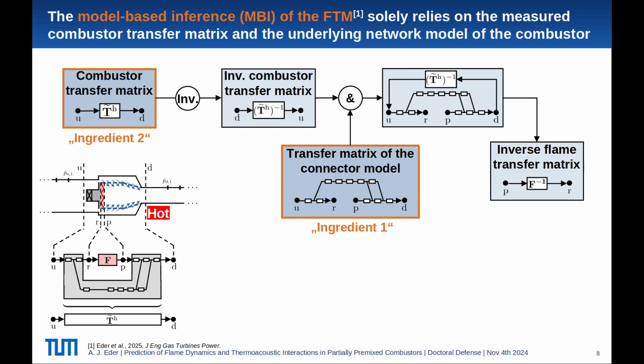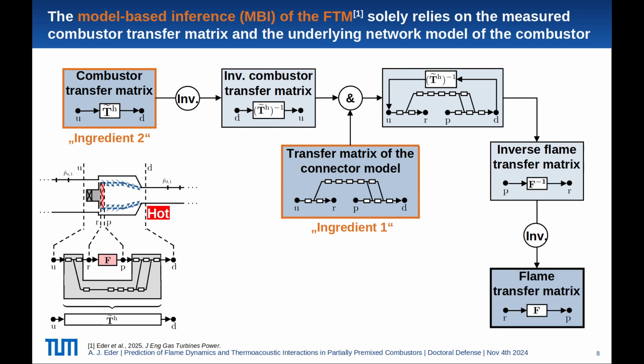We can again invert that, end up with a flame transfer matrix, and have exactly what we want to have, out of which we can optionally also extract the flame transfer matrix. Our approach is called model-based inference because of exactly the reason of ingredient number one: it's model-based. So in addition to the experiment, we need a low-order model of our combustor.